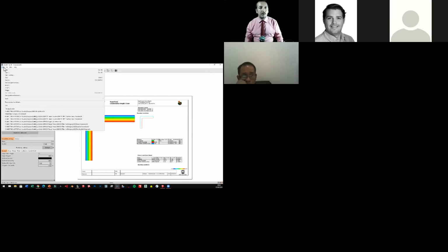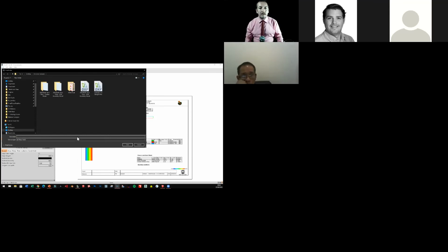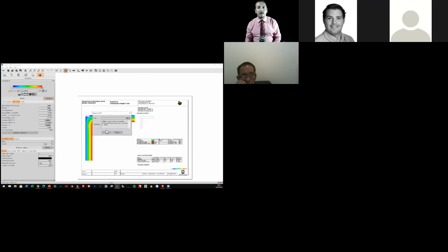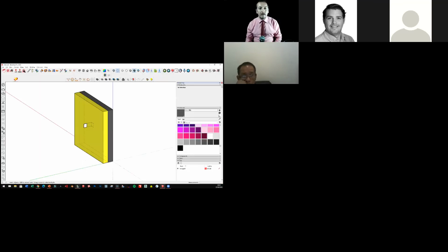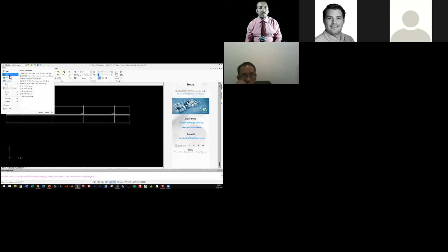Actually, just before we go any further on this one, if you export this as a DXF, convert it to millimeters or inches or meters or whatever you want. Just type in the scale. And then if I go to CAD, file, open.